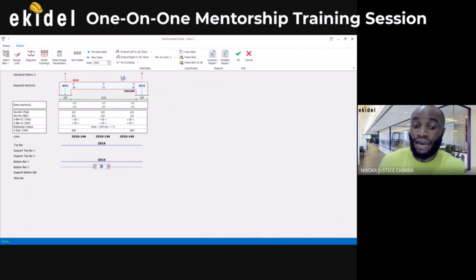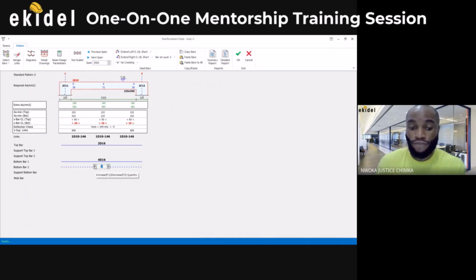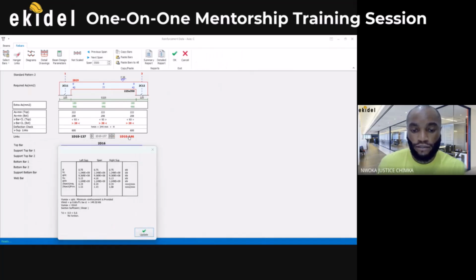Now, if you want to add additional bar, for example, this top bar can still have additional bar, or bottom bar can still have additional bar. For example, if this building was very massive and having heavy load, and we have increased up to 4 numbers, just to avoid it being too tight, like the rebars, you can have a new layer at the bottom. I don't know if you know that. So you can add a layer here, and come here and call it layer 2, which is already here, layer 2, and then make it lap. So if I show the drawing now, let me say update again, updates.